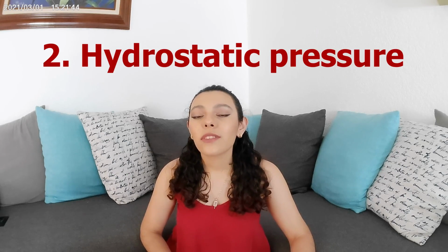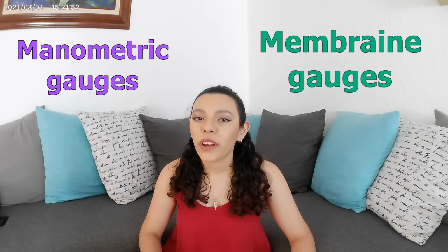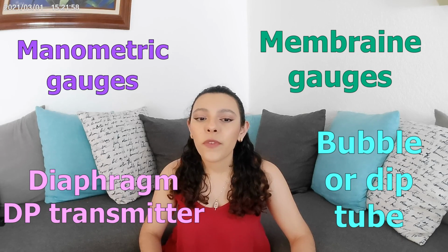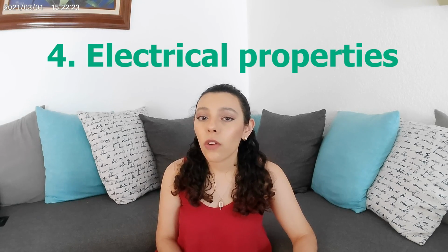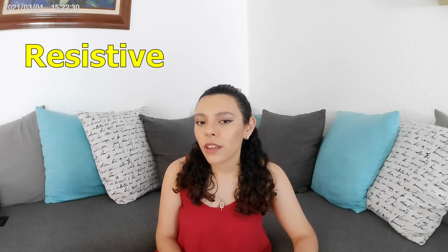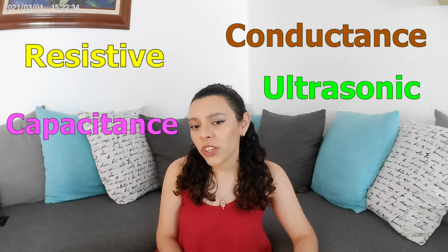2. Hydrostatic pressure, which is used by manometric gauges, membrane gauges, bubble tube or dip tube systems, and diaphragm differential pressure transmitters. 3. The difference produced in a flow by the processed liquid. Or 4. Taking advantage of the electrical characteristics of the liquid, whose methods are resistive, conductance, capacitance, ultrasonic, radiation, laser, and radar. Today I will talk about the direct measurement instruments.